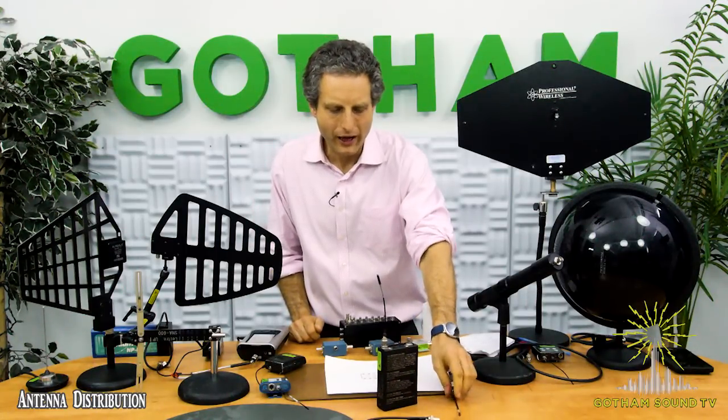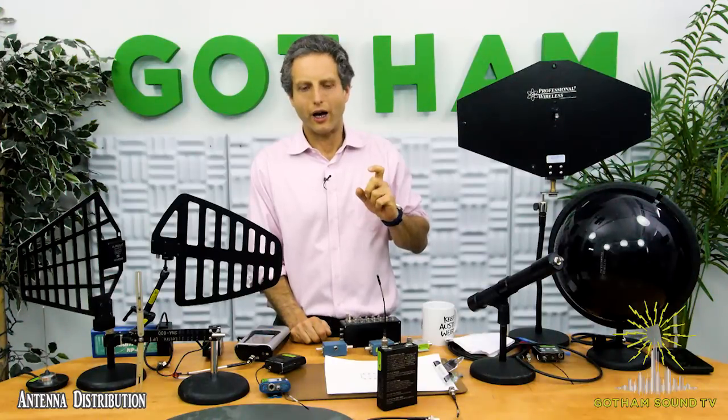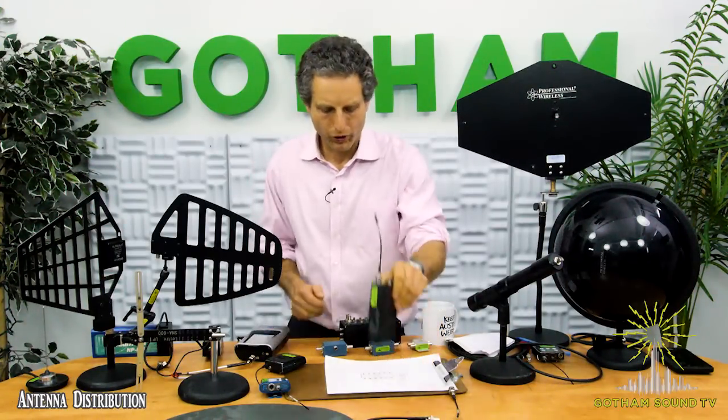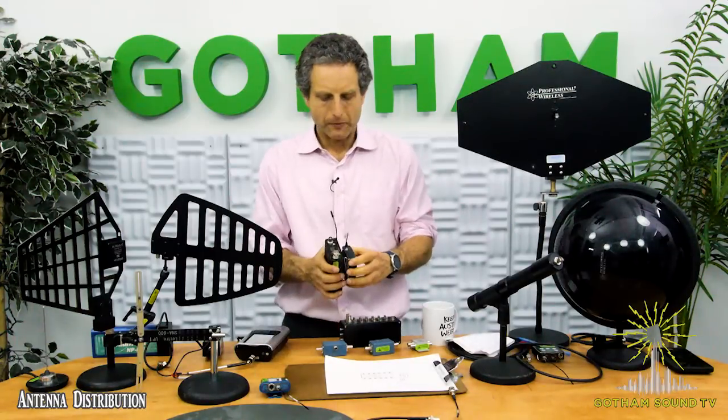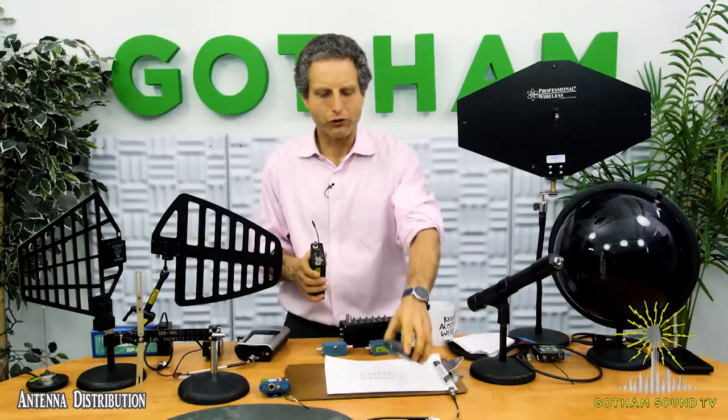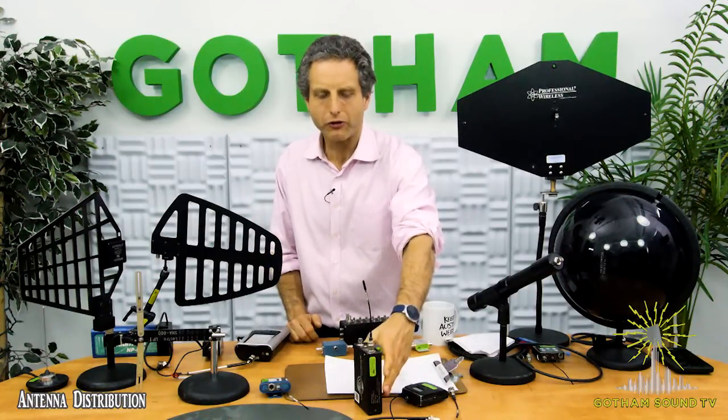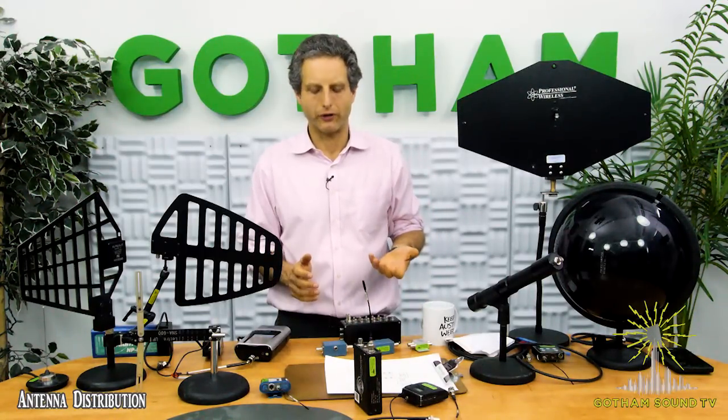The answer is that if you're going to use a BNC T, which I don't recommend, you lose isolation. When you have multiple receivers in a bag, the antennas are not isolated. A BNC T is totally passive and completely bidirectional. It'll pass signal in any direction. You still don't get the isolation between receivers that you need.